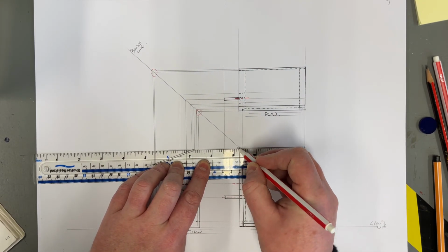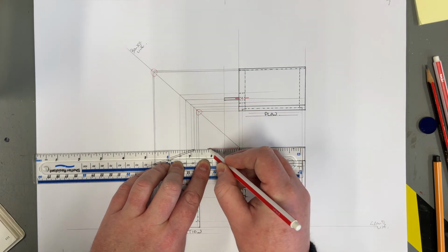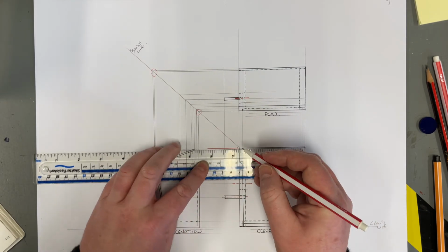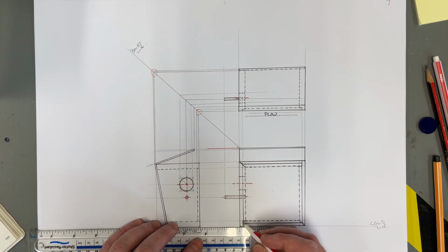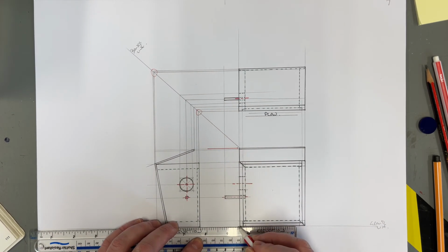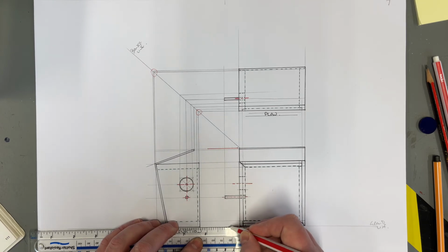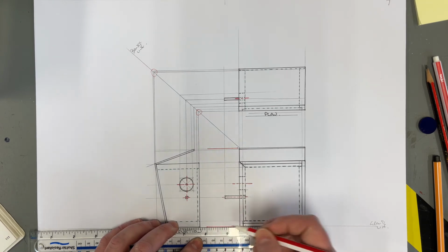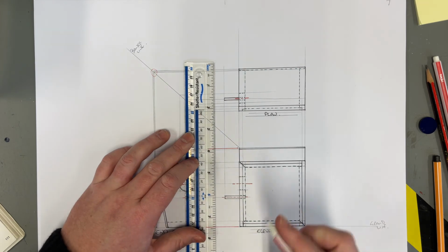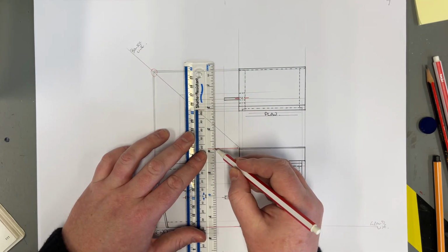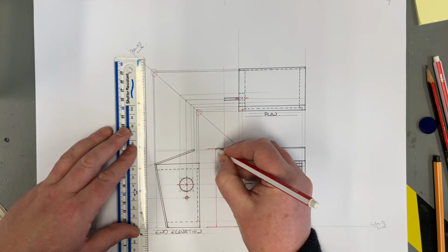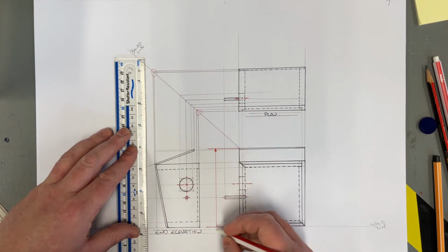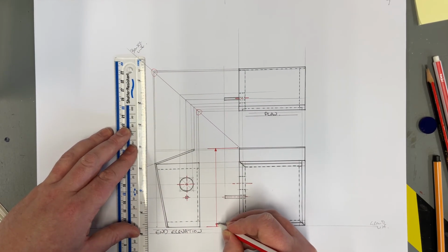It's a couple of millimeters off and comes out and extends to about there, all the way down to the bottom for height. Another leader line, leave a little gap, project across, and then the dimension line itself that touches the 2 leader lines with short, sharp, filled in arrowheads.